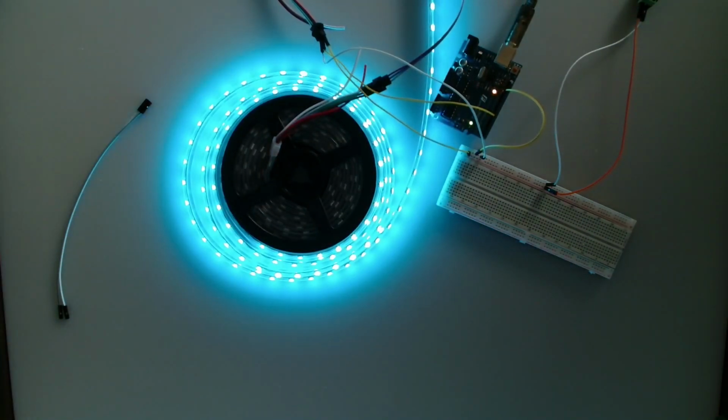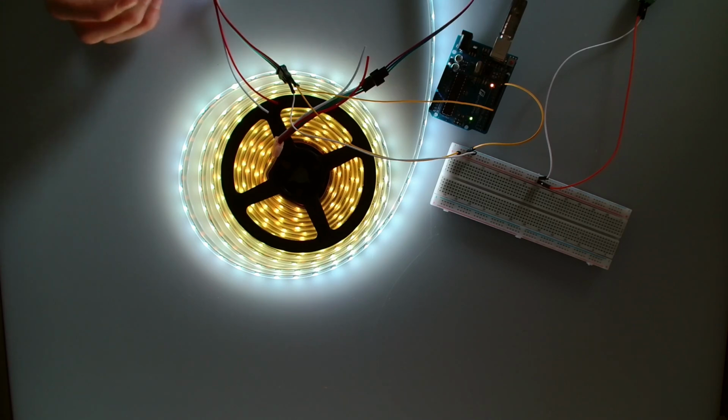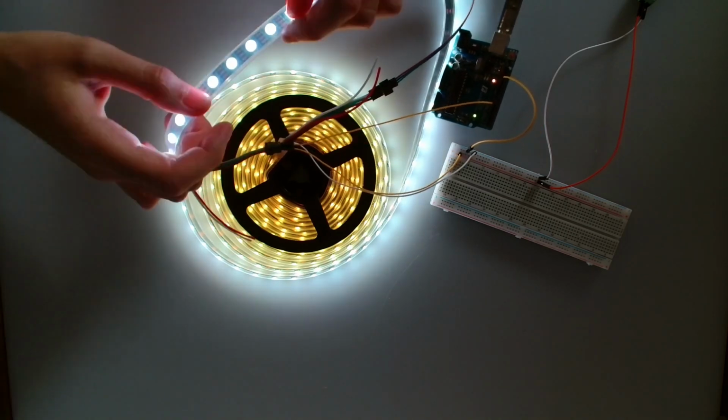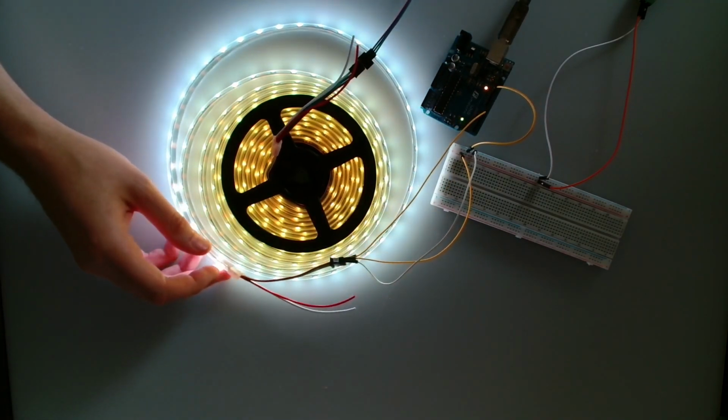Like so. One thing you do get when you up the number of LEDs that you're powering, so here we're powering now the whole strip, 320 LEDs, with just the power supply on one end, and it's just a 5-volt power supply. These are all at 150 in each channel, and we're getting a decent whitish light at one end, but it drops to yellow at the other, and that's purely because of voltage drop.